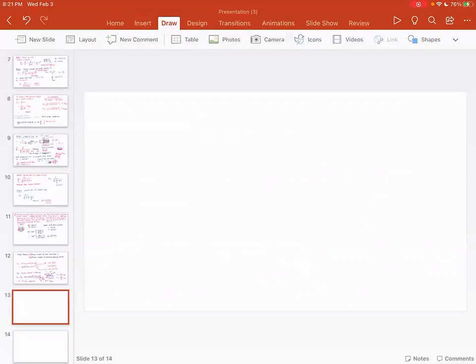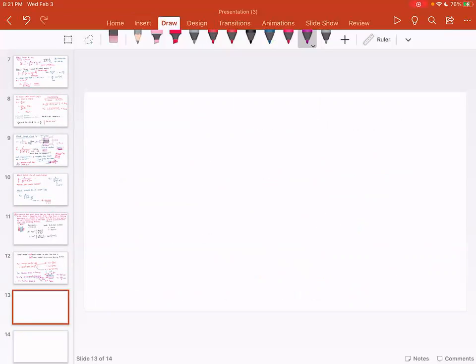Now we have to find out the force at the end of the 400 millimeter lever arm. To find force at lever, the lever arm is 400 millimeters. We know force multiplied by lever arm is equal to torque.